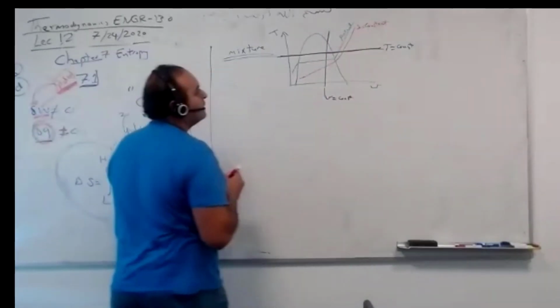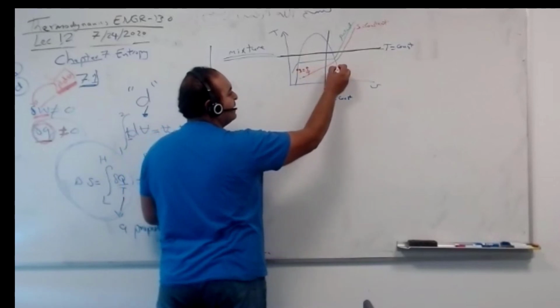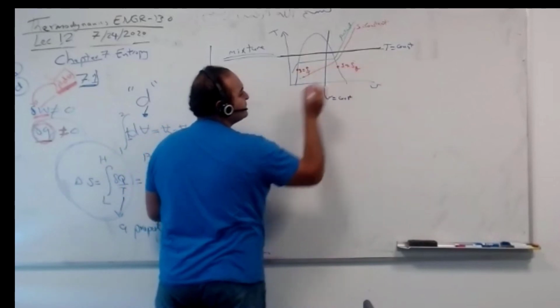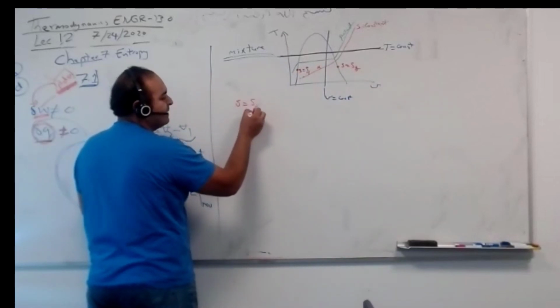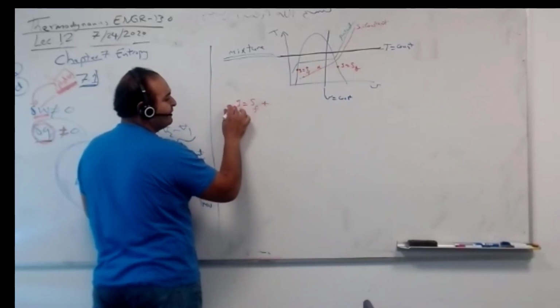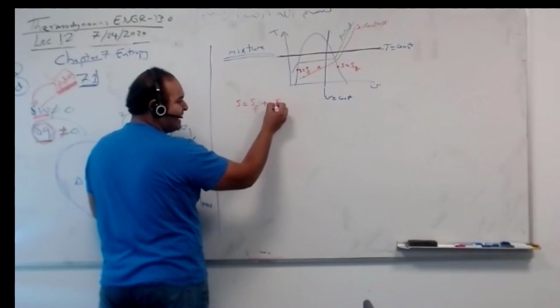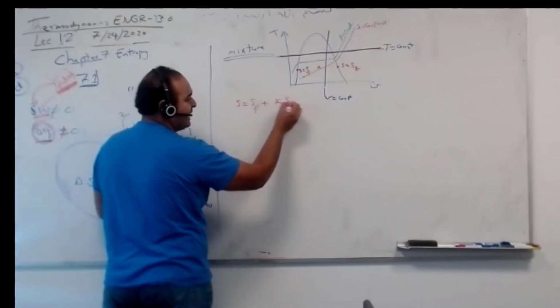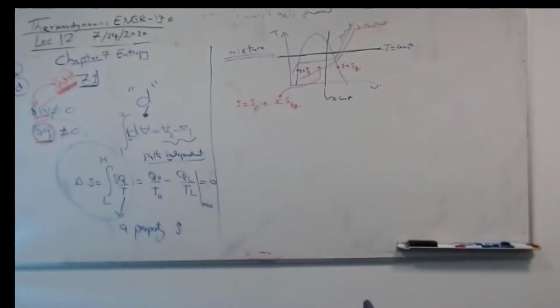S. If you are here, S equals SF. If you are here, S equals SG. If you are here, S equals SF plus, can somebody tell me, plus what? X SFG, X, quality first. My bad. The same equation we use for V, specific volume, we use for internal energy; the same is valid here, everything applies.